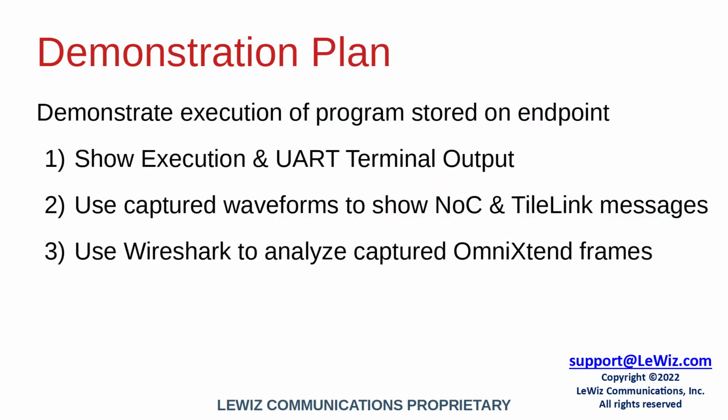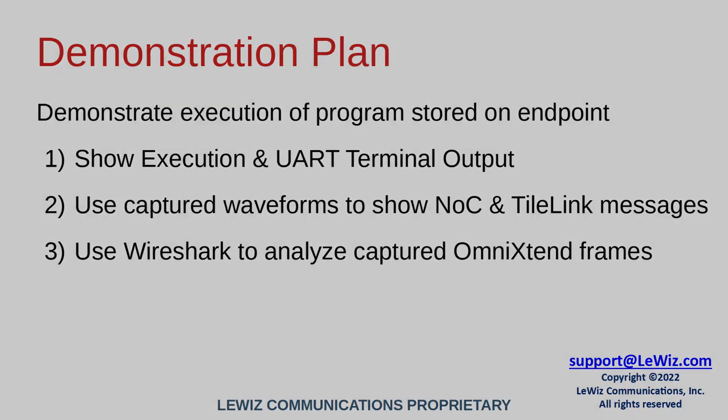For our demonstration, we'll be showing execution of a simple Hello World program stored on the endpoint. First, I'll run the program and show its output on the UART serial terminal. Next, we'll examine the NOC and TileLink messages from the waveforms captured by the ILAs on the VCU118. Finally, I'll use Wireshark to analyze the captured TLOE frames sent across the network.